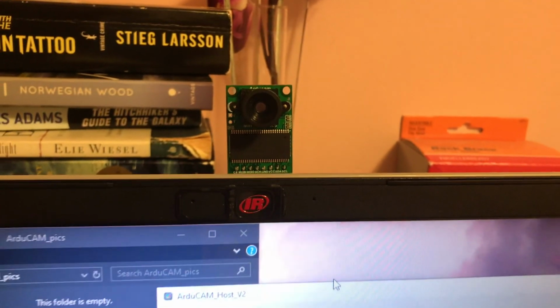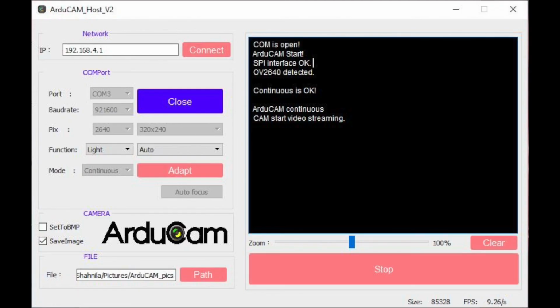After we've made all of the proper connections as shown in the block diagram, we run the ArduCam GUI. The GUI consists of several camera options such as turning the camera on and off, pixel options, different functions and filters, and singular and continuous mode. Singular mode means that every time the capture button, now replaced with the stop button, is pressed, a photo is taken. Alternatively, continuous mode will record the screen and save images of the frame through time until the stop button is pressed. There is also the option to save images onto a local directory.